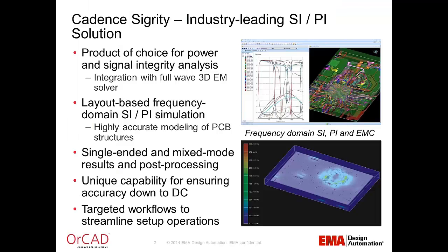All right, well, this product's based on the Cadence Sigrity technology, which is the industry-leading signal integrity and power integrity solution today. It's known for what's called power-aware signal integrity, so it's usually the product of choice for just about everyone doing signal integrity analysis today. You have the option of even including a 3D field solver if necessary for things like three-dimensional via analysis and difficult return paths. That's usually where 3D comes in, but in most cases you don't really need that. However, sometimes that is an issue, and so the 3D field solver is fully available to you.